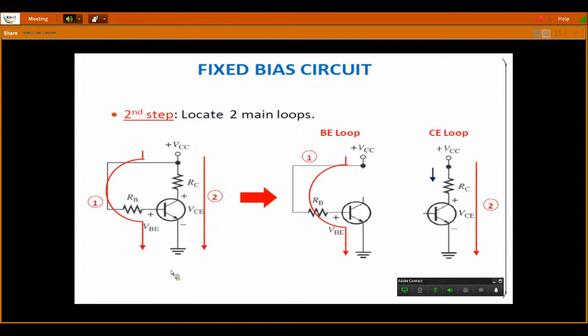Now we have to analyze what the base current is and what the amount of collector current is. So the collector quiescent values we have to maintain as a constant value. This should not depend on either beta, or temperature, or the reverse saturation current under reverse bias junction voltages.